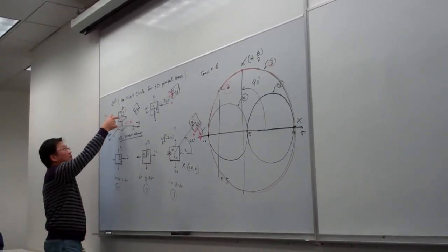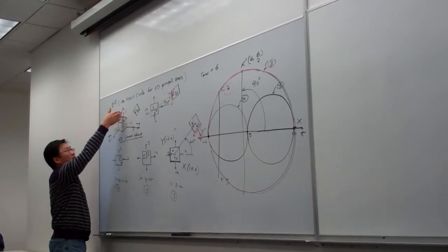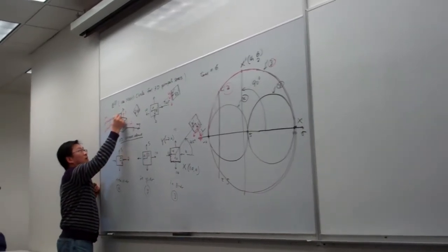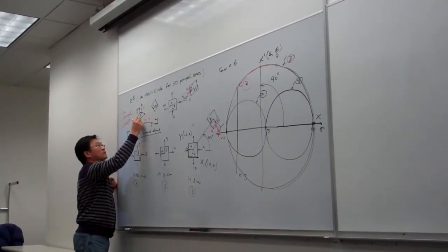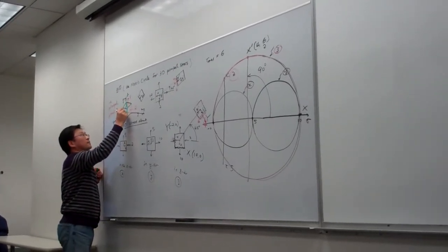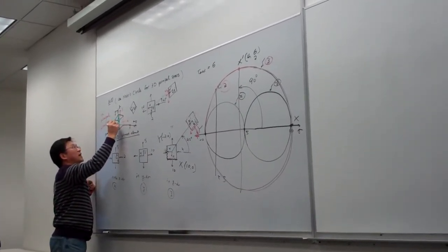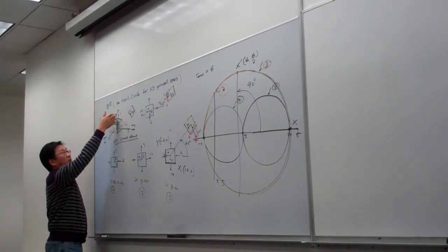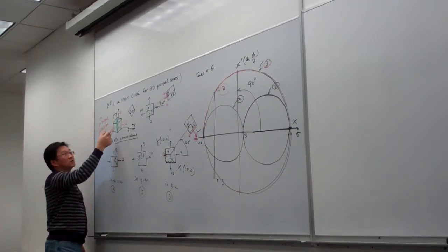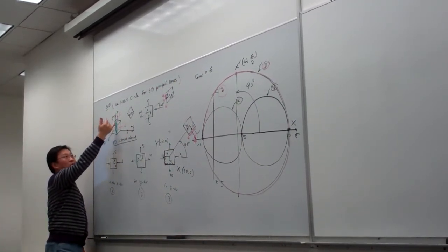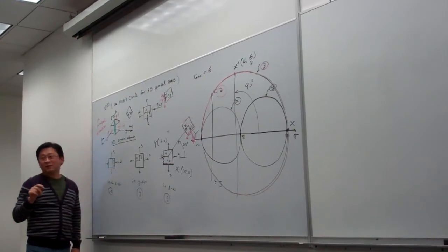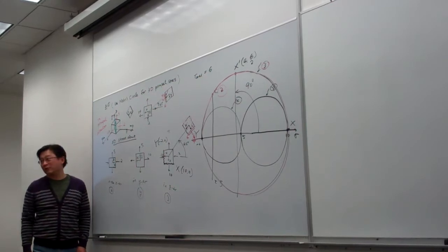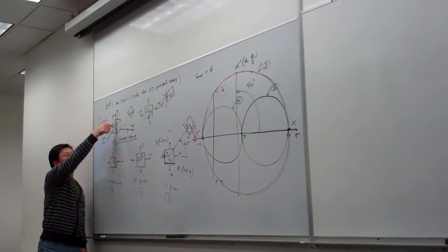Again, you look at this cube, and we rotate about the z-axis by 45 degrees. In that specific orientation, that will be a line cube, which I'm going to draw here, this green plane. This is the diagonal plane in the orientation we talk about. We're rotating this one about z by 45 degrees. So in the orientation parallel to the green one, if we were able to measure, we would find the maximum shear stress equal to 6. That will be in this orientation drawn here.